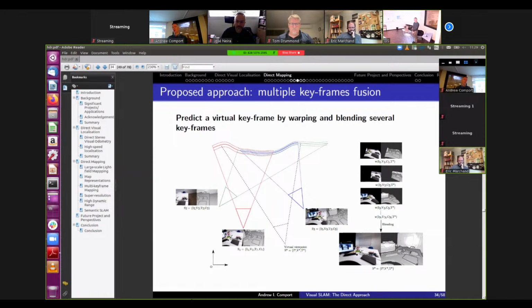Then you have the multi-resolution pyramid, which allows you to smooth out and look at more global information, which helps to make the convergence domain bigger. And in some cases, if we know the movement of the robot or the car, we can predict it to help remain close to the solution. And then in the end, if it does end up breaking down, we have implemented a fast local relocalization. So we just detect when we've lost tracking, and then search for it until we get it back. So it's more of a technological approach to solve that.